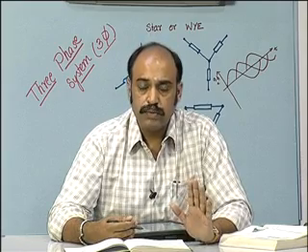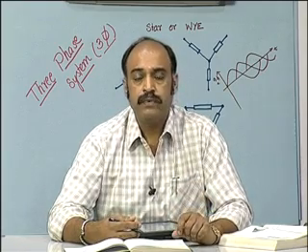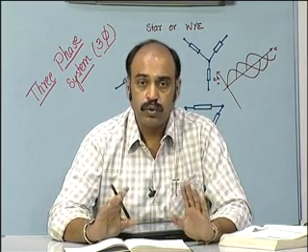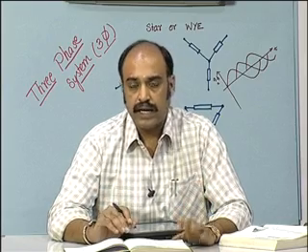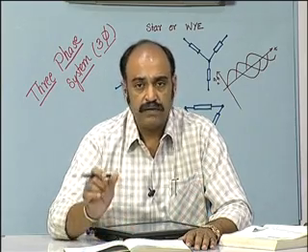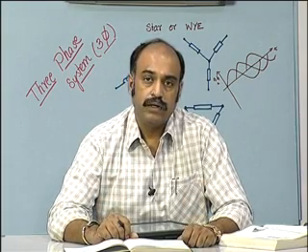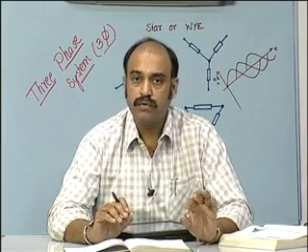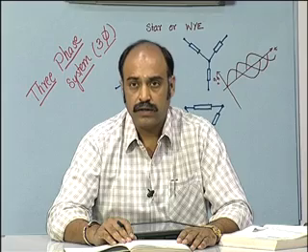The best method to measure the power in the three-phase circuit is by means of an oscilloscope. You measure the voltage using a voltage probe and a current probe together. You measure the line voltage and the line current, and then compute root 3 EL IL cos phi, and the phase difference can be obtained from the voltage and the current waveforms that can be seen on the oscilloscope. That would give you the best method. It is independent of whatever the power factor may be.